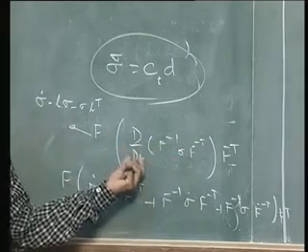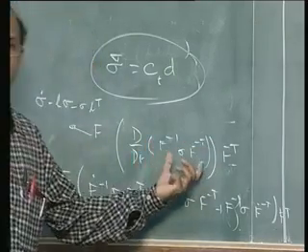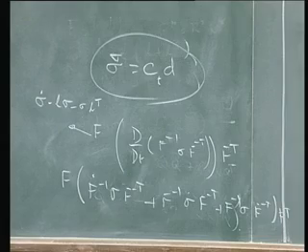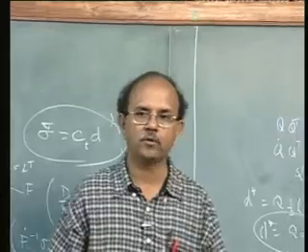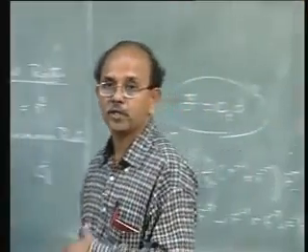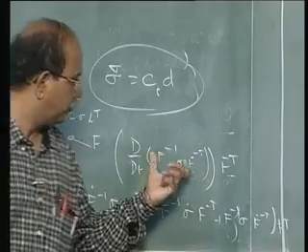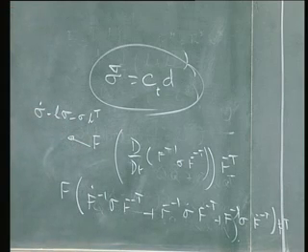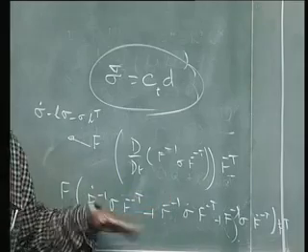This is the pullback derivative push forward. So this sigma is pulled back. You can have a look at our old notes. Pullback derivative, then these two are the push forward operations. Note that for contravariant quantities and covariant quantities, we said that the pullback and push forward operations are different, in the sense that the equations are different. Sigma being a contravariant quantity, the pullback and push forward are different from what you would do in the case of, for example, strains. So the meaning becomes clear here, right? So the Oldroyd rate is another rate that is used in the constitutive equation.